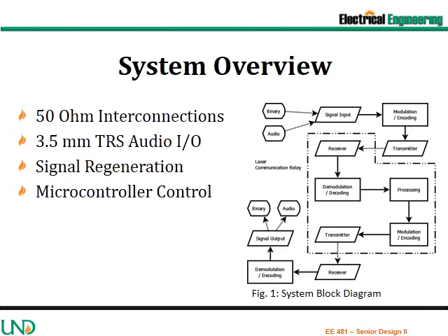The processing section will utilize signal regeneration for FM, amplitude shift keying, frequency shift keying, and phase shift keying. An automatic gain control circuit is required to regenerate AM signals. High power, high speed devices are utilized for this project. The purpose of utilizing these devices is to allow for exploration of the capability of the system without running into device performance issues. Lower speed devices may be utilized based on performance requirements of the application.